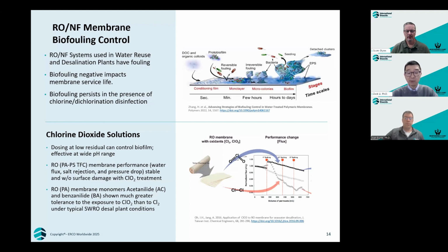Chlorine dioxide provides a viable solution. Chlorine dioxide pre-treatment has proven more effective disinfection and biofilm control with both media filters and cartridge filters. Chlorine dioxide pre-oxidation combined with low-pressure membrane processes, including microfiltration and ultrafiltration, reduces footprint and increases production capacity and protects